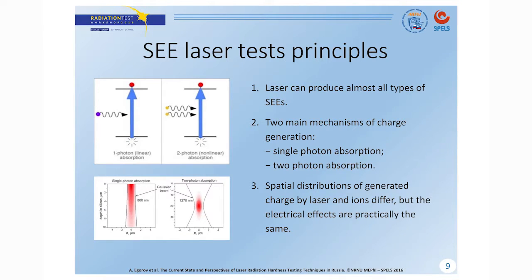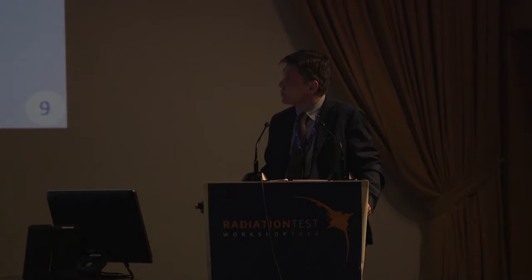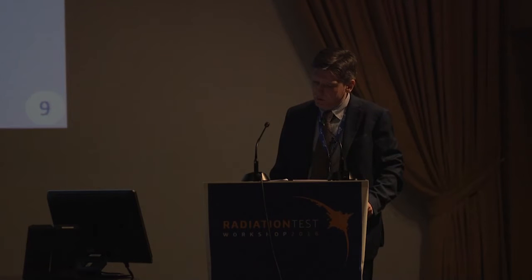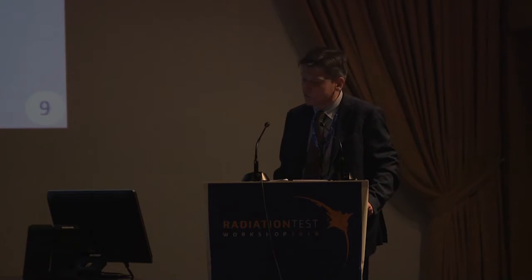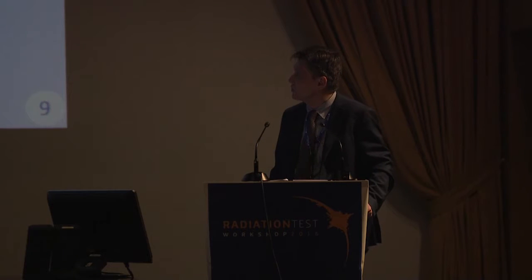And the application of the latter technique is somewhat more complex. Because of the nonlinear nature of this effect, we use two photon absorption only for research, not for qualification tests. Although the spatial distributions in these cases differ from that of real heavy ions, it is often possible to simulate similar electric effects in both cases. And that's the basis of laser simulation.